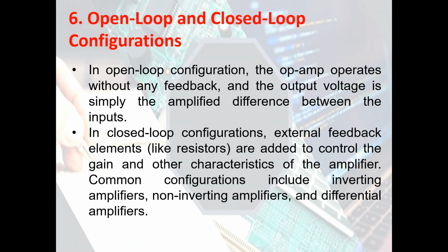As per the closed-loop configuration, it is designed to provide stability, precision, and control over the amplifier's characteristics. It is widely used in practical applications where the output needs to be well-defined and stable. In a closed-loop configuration, number one, the feedback path is closed, meaning there is a feedback network that connects the output back to one of the input terminals, either inverting or non-inverting.